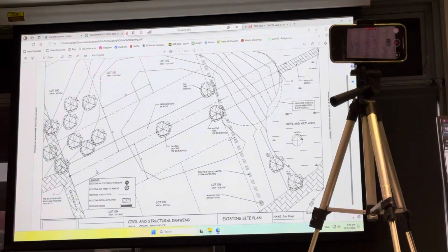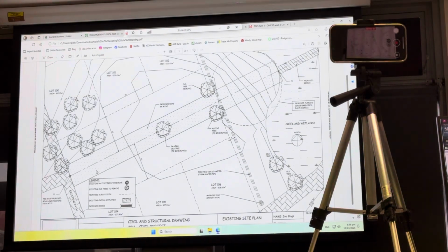So you're going to tie in, and you don't want that much of a gap to tie into the next bit of road. And you don't want it to miss either, because you tend to run off the road if it misses. So the tie-in point is very critical, because they mark that from day one, and that's what they match into, all right? Therefore mark it. Sometimes it's determined by P1 or P2, but normally it's marked.